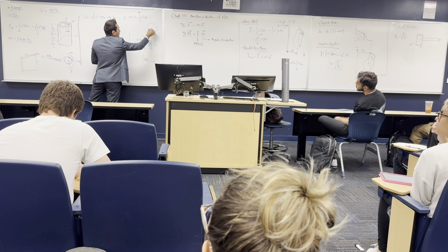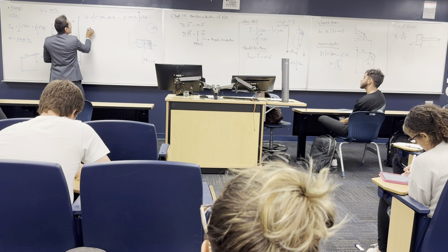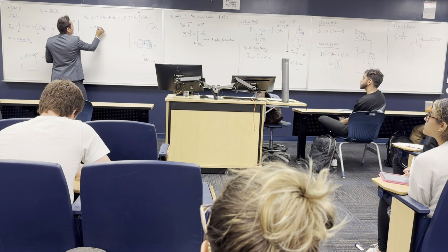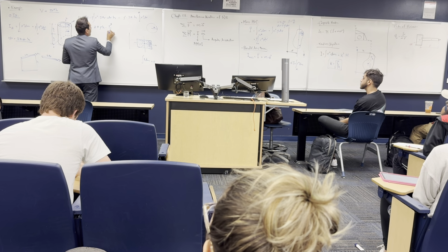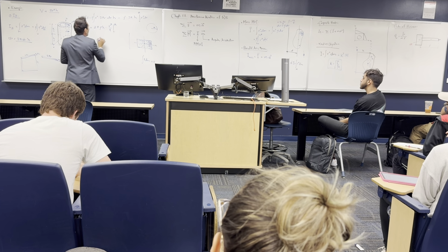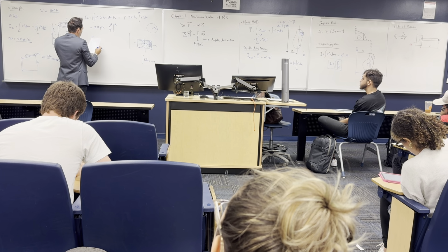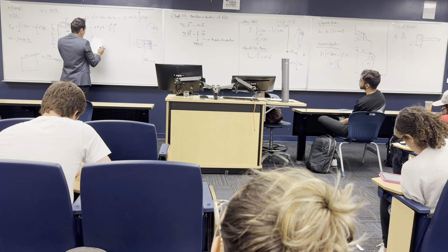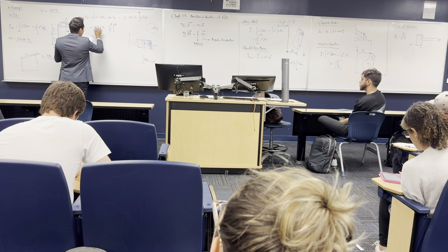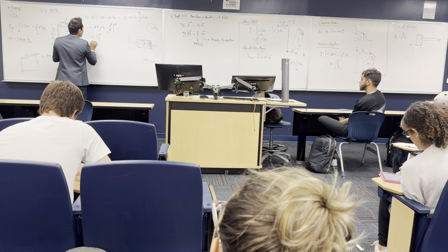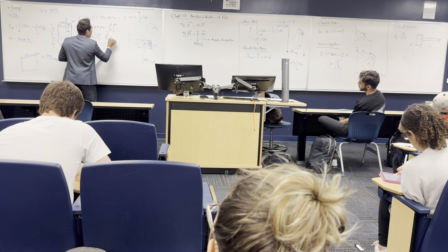I have my cylinder like this from the top. I want to integrate from here until I go all the way down to the big R. So this is going to be 2 pi rho h multiplied by r to the power 4 over 4 from 0 to R. So this is going to be rho pi over 2, and you will still have the R to the power 4 when I substitute with this, multiplied by h.